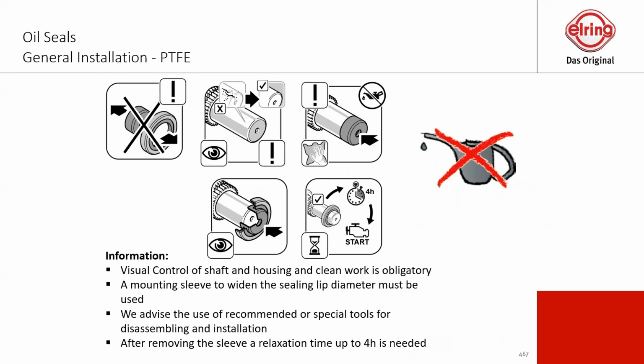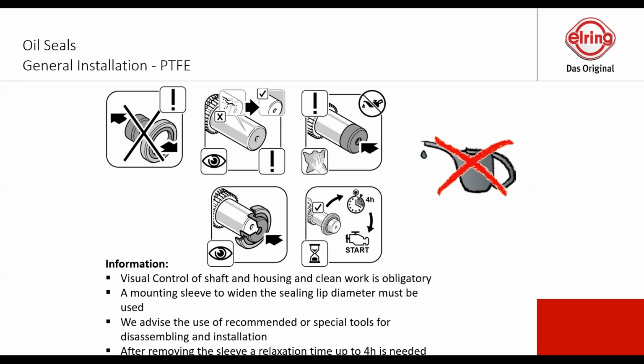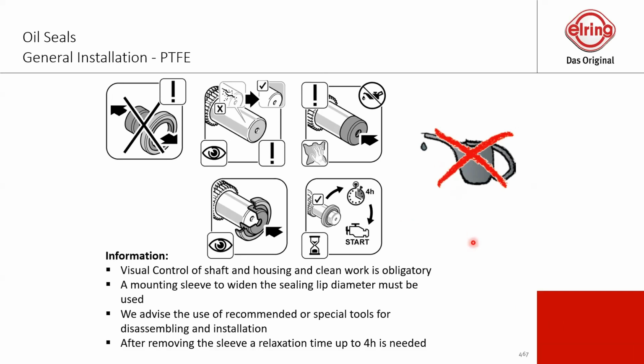So if you receive this and it is not sitting in an equal way inside, then I would not recommend installing an oil seal like this. Only if you see by yourself that it's in perfect condition. Otherwise, you have to do the job again, and you don't want that, because it's double the time you waste for the installation of an oil seal.